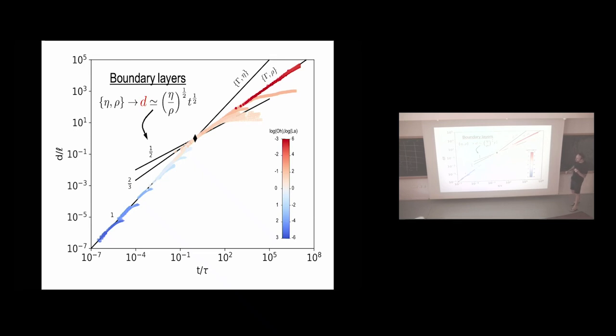There is only one condition, which is that the three quantities that you choose on the table should not be aligned. So if the three quantities that you choose, for instance, are on the same line, this will not be the case, and you can think about this case on your own. But as soon as the three quantities are not aligned, they're going to generate three lines, three power laws, and the power laws are going to intersect at the same point.